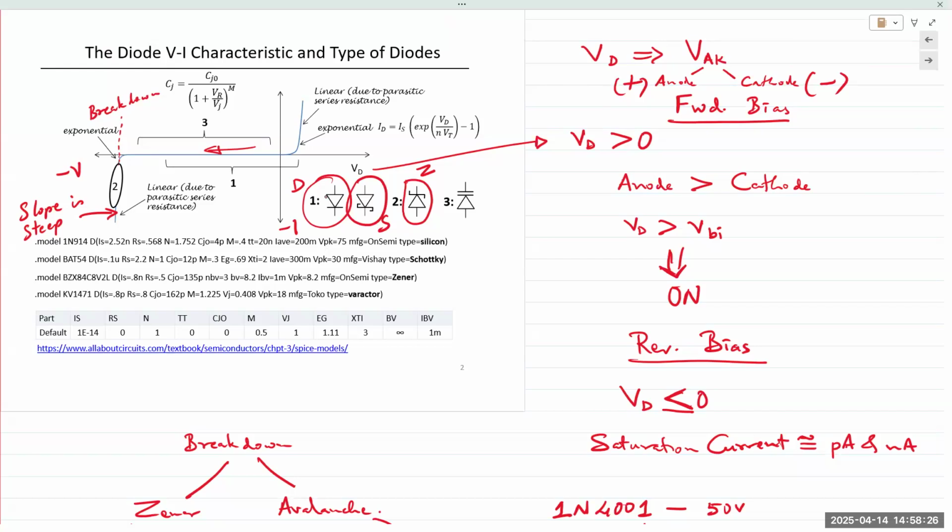The special thing about this diode is that it's made up of one semiconductor material and one metallic material. So the junction is metal semiconductor. It's not semiconductor to semiconductor. It's metal semiconductor, so there's always plenty of free electrons available. Free charge carriers are always available. This results in a very low potential barrier. And so these diodes turn on at low voltages like 0.2, 0.25 volts. Also the speed of operation is fast, which is what we have been using in the lab. Fast switching, fast operation.